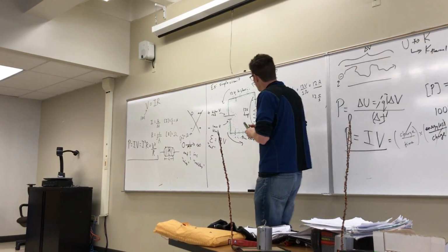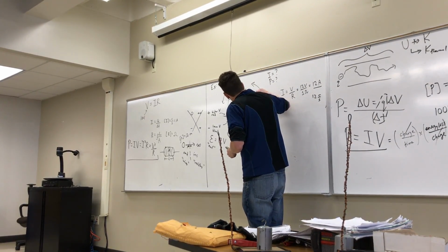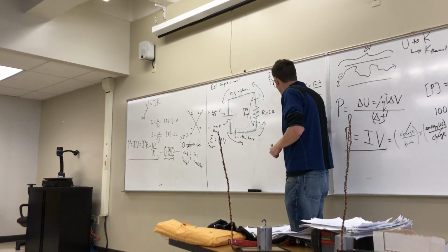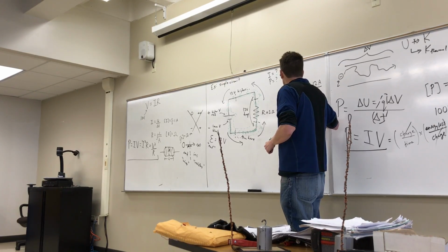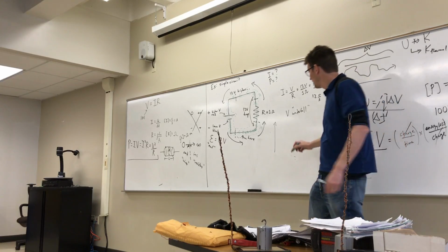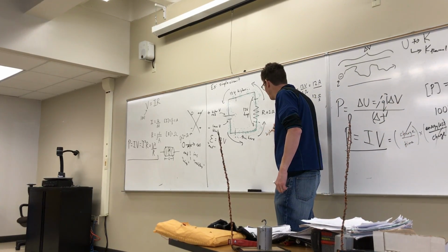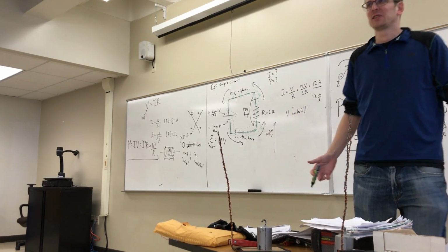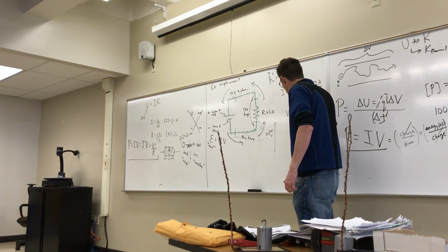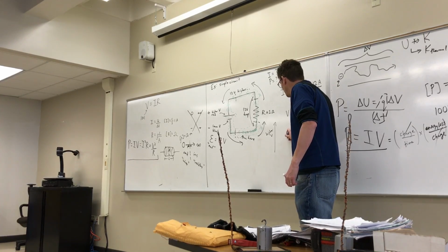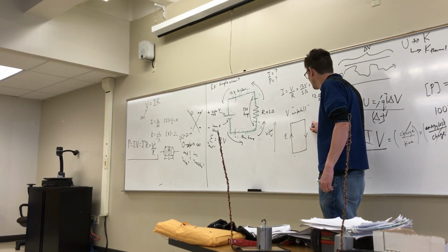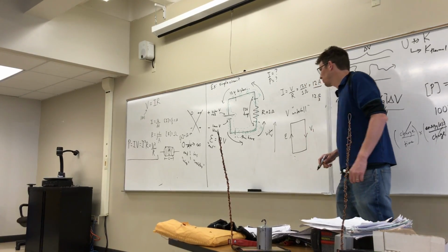So one of the things I do sometimes is I'll label this as equipotential A and this as equipotential B, and then I'll make what's called a voltage waterfall. The rule for this is that if you're higher on the page, that's higher voltage. I always like to orient vertically because I'm always tied back to gravity, right? Higher on the page. And so that looks like this. So there's the battery, and there's the resistor. That's the amount that drops across the resistor.